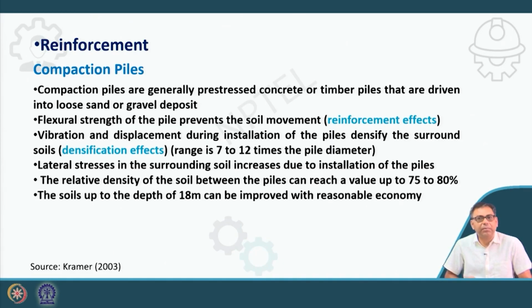So, we are inserting the piles into the soil so that the movement of the soil can be restricted by this reinforcement effect. Vibration and displacement during installation of the pile densify the surrounding soils. So, if you are using it for loose sand, during installation there will be vibration and displacement. Because of that, some densification effect will also come into picture.